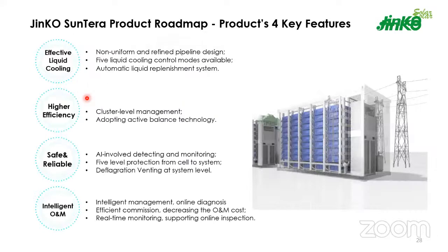So altogether, in totality, if you see the effective cooling mechanism happening through liquid cooling, it is one major parameter, a design innovation which has happened with reduced auxiliary consumption, which is why it is more efficient, with high energy density. Instead of going with 280 Ah or 100 Ah batteries, it's now moving towards 300 to 306 Ah for this particular quarter. And it's completely reliable and safe because it's monitored at the cell level itself for temperature, and 5 temperature zones are being considered for the same, which is why it's more reliable.